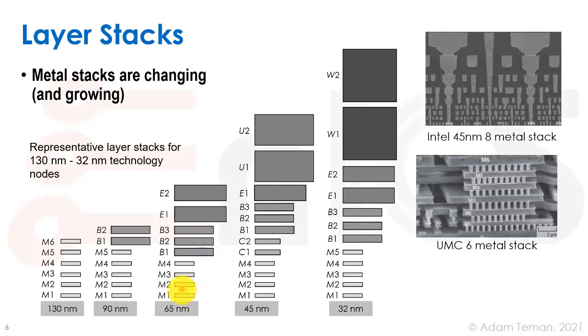And so we would be able to go up through vias up to one of these layers and go farther in the chip. For example, clocks will usually try to be in these types of layers. And then we would have these top layers that are almost exclusively for power and maybe for some of the trunks of the clock tree. It can even get more than that. We can have 4 types of layers and more, and the top layers become really, really thick.